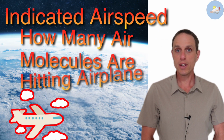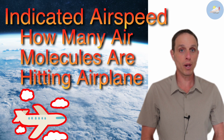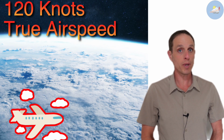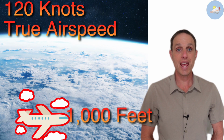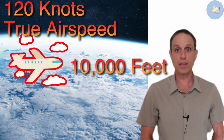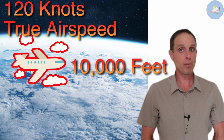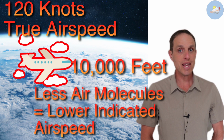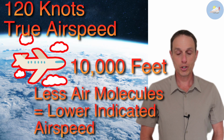I like to think of indicated airspeed not as speed, but as a measure of how many air molecules are hitting the front of the plane. Imagine a plane flying at 120 knots true airspeed at 1,000 feet. Now, let's have it climb up to 10,000 feet, still flying at the same true airspeed. Because the air is thinner up there, fewer air molecules are hitting the plane, so the indicated airspeed would be lower.